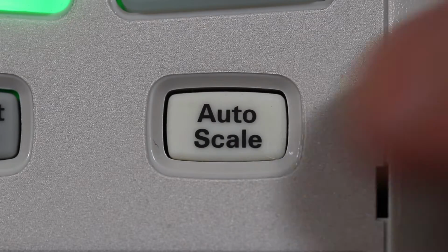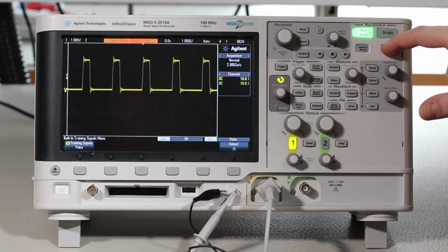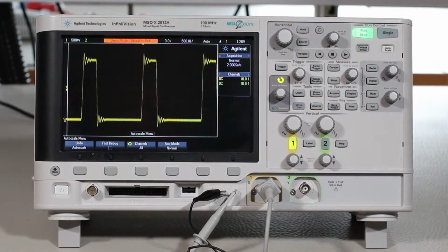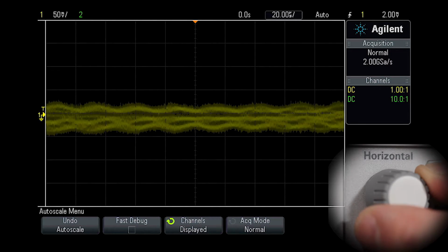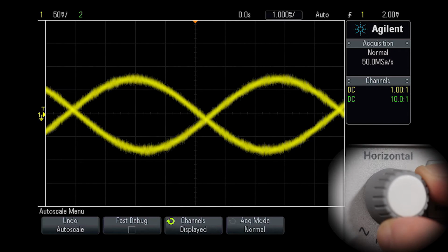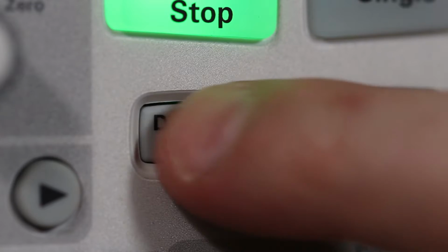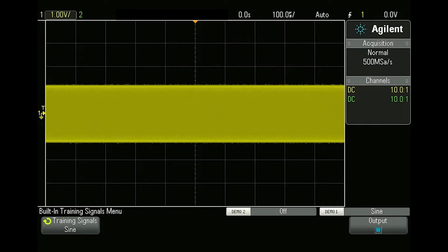Most digital oscilloscopes have an automatic setup button which adjusts the voltage and time scales to zoom in on the signal. Whilst this function is useful, it shouldn't be relied on, as the calibration will adjust to the peak-to-peak signal that the software identifies. This might just be part of a signal with recognizable variance, and the main signal could be ignored. For this reason, it's always recommended to start with a default setup and zoom into the signal.